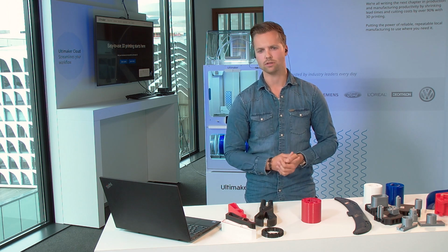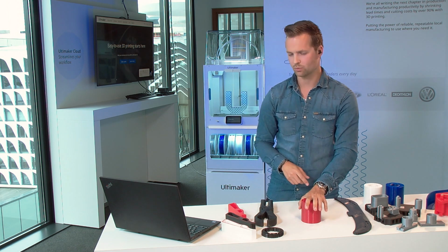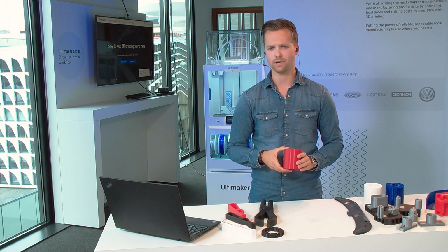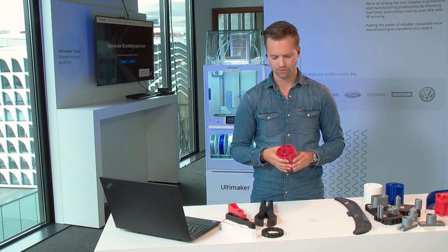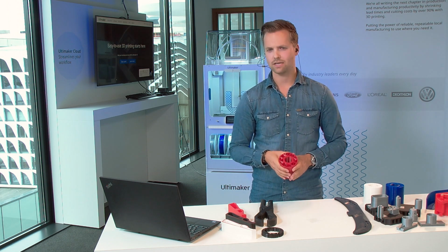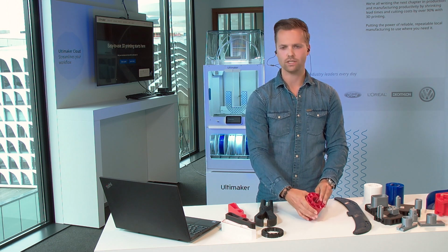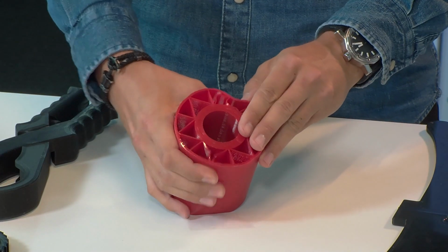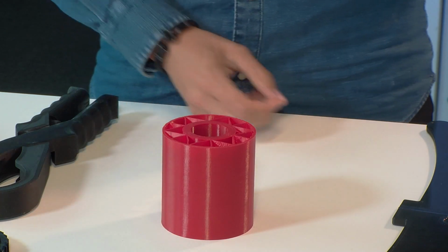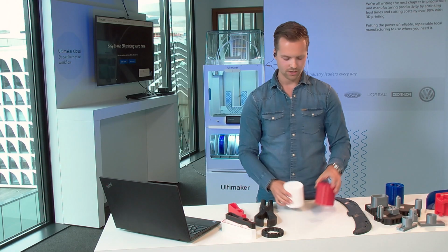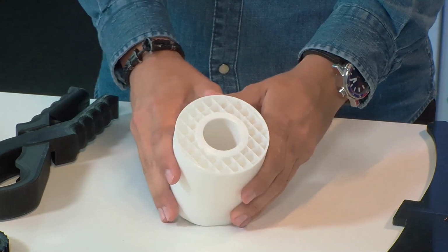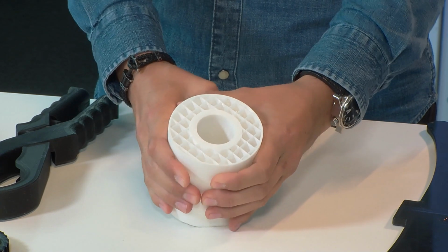Didn't really look professional. So we tackled this with Ultimaker TPU 95A, which is the flexible material. And we tried different kinds of infills to get this dampening effect. What you see here is the triangle infill. So when I squeeze it, you can see, oh, there's a nice dampening effect. And the cool thing in Ultimaker Cura, you can change the pattern to, for example, a grid to have an even sturdier part.